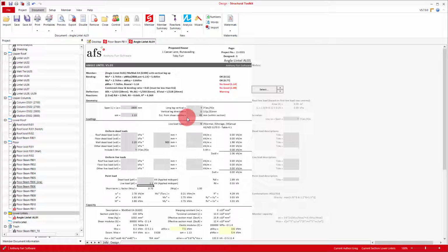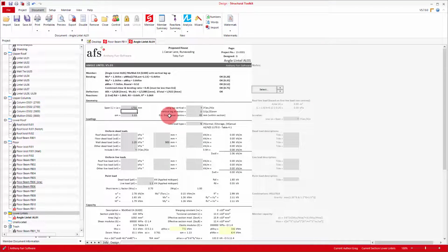Brickwork generally requires a lower tolerance of deflections, and so we'll be aiming for a span on 500 for dead load and span on 360 total. So we'll start slowly decreasing our span to meet this and the design capacity checks. Skipping ahead, we've arrived at 1750. What we can do now is keep going up a size and work out what span will work for each.